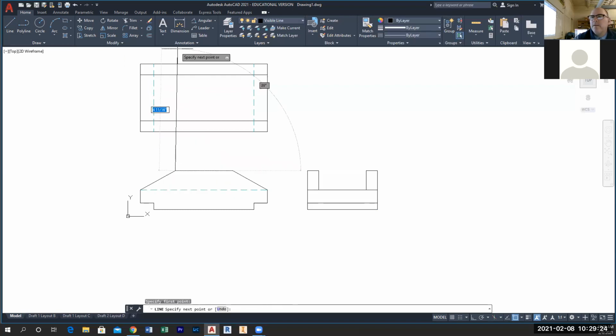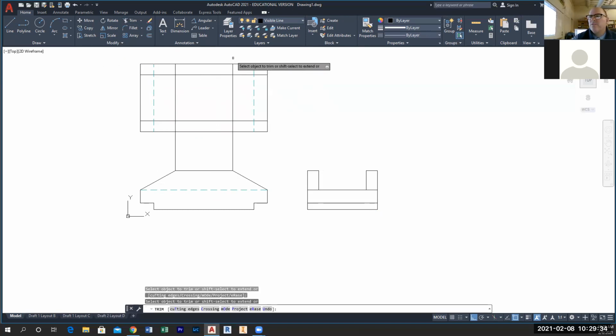I can go from here. Let's hit ortho because I need it to be straight. Pick that. Let's go line. We got ortho on. Let's just pick that. And then what do I want to do? Trim. Trim that. Trim that. Let's trim, trim, trim, and trim. This line right here represents this top edge right here and this angle right there where the line comes here and then it starts going down. That's that line right there on this side and this side on both sides, this side here and this side here.